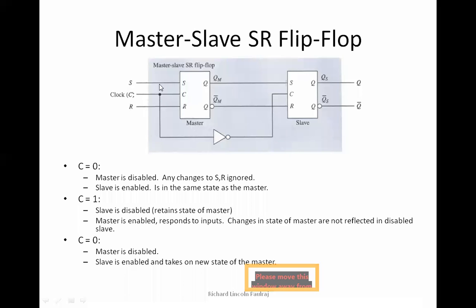When it's not functioning, the values are held. If the values are held, then it is called a latch. Latch means connecting to something, holding on to something. If it's holding a 0, then I can call it a 0 latch. If it's holding a 1, then in simple terms it is a latch holding the value 1. In general, we just term it as a latch.